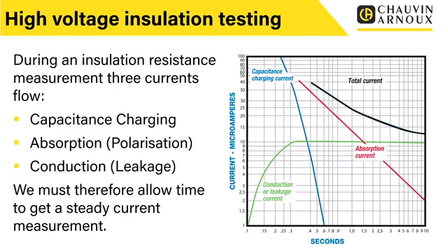Now obviously if we took the test readings or monitored them during that time, we would get a changing value of insulation resistance, and it wouldn't be the true value of insulation resistance. So we need to make sure that we've applied the test current for long enough that we've got past that point at which the capacitance within the circuit is charging up.